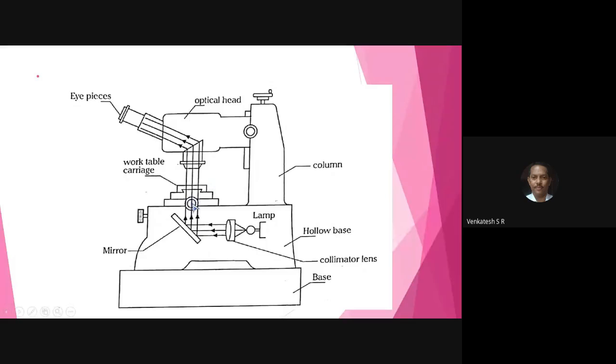This one is the micrometer symbol. You can turn it clockwise or anti-clockwise so that you can measure the distance between two peak points, which is the pitch of the thread. The two peak points of the thread in opposite direction give the major diameter, and the portion of the thread below the upper portion is the minor diameter.